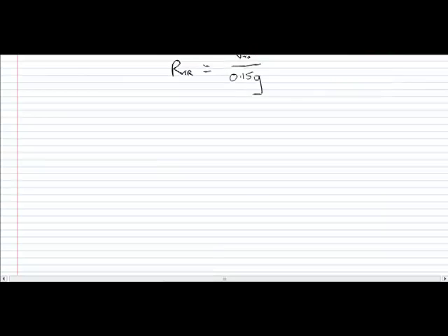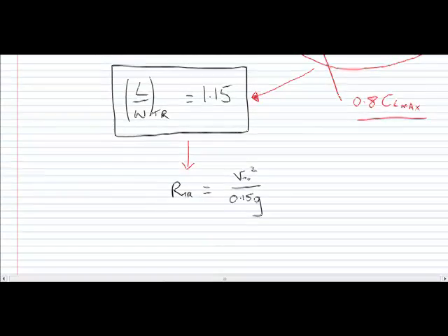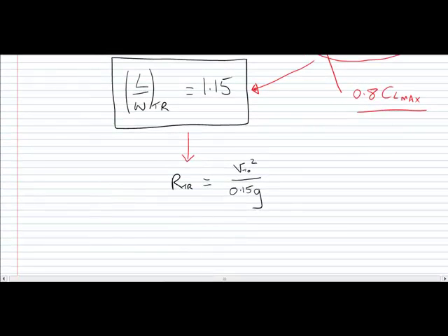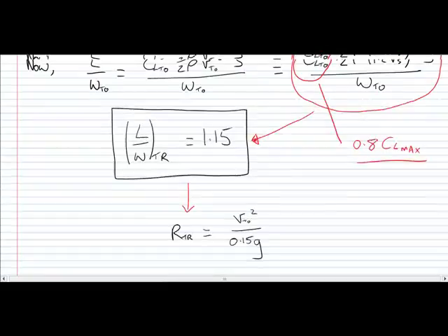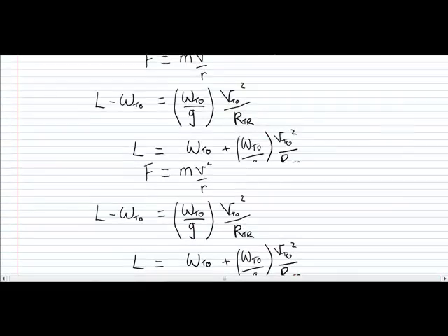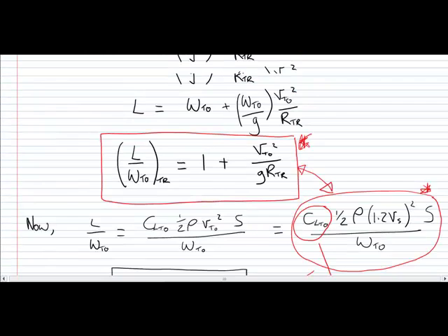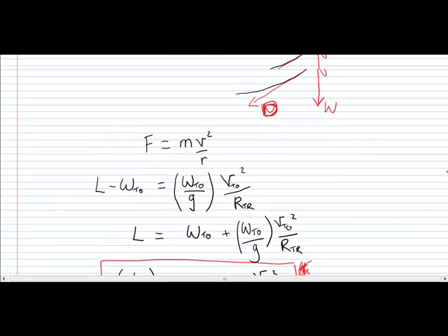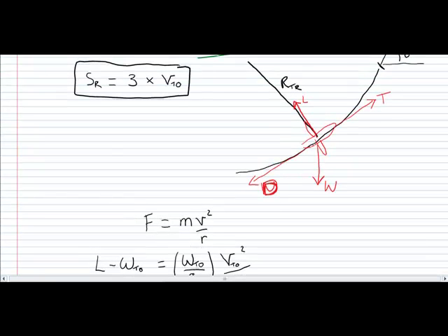And at a constant climb, if we assume a constant climb velocity and the forces are balanced, so if I go back up to our aircraft going around this, if we assume that the forward velocity along this flight path is constant, then we know that thrust must equal drag plus W sine gamma.